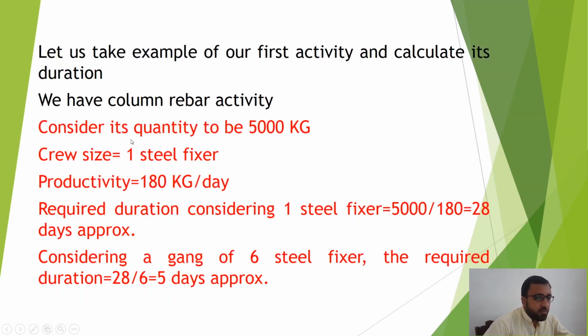So let us take the example of our first activity and calculate its duration. We have a column rebar activity. Consider its quantity is 5000 kg. The crew size is 1 steel fixer. Productivity is 180 kg per day.